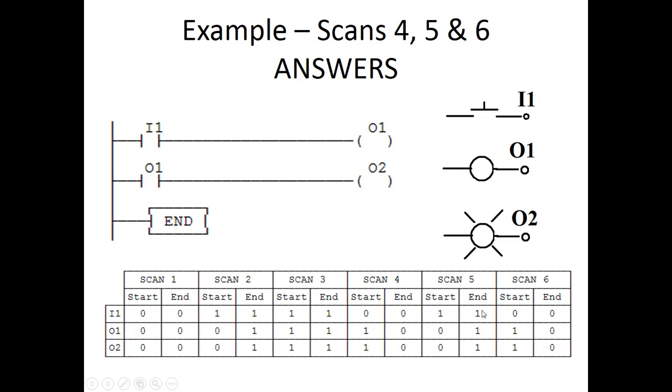Okay? And so once again, you hit start, and these start at 0 because that's where they were before, and it solves and everything becomes 1. You let go of the push button. These remained 1 because it hasn't solved the ladder. But here's the ladder. It solves the ladder and updates the outputs to zeros. So it's a little more detailed on how the scan is working.